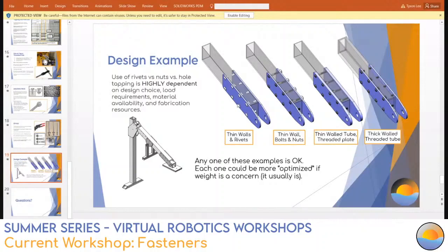Okay, and then another one on welding is from Todor again. Are there any pointers you could give on welding, when to use or not to use, etc.? I think a drive base is really good for welding, because once you've defined that drive base, you want it held together tight, and that's a really good application of having a welded structure. Then you get outside of that, in an FRC robot on an FRC season, now you're talking about modularity, where you don't necessarily want to commit yourself to a certain design or a certain fabricated part that's completely welded and you can't go back onto.